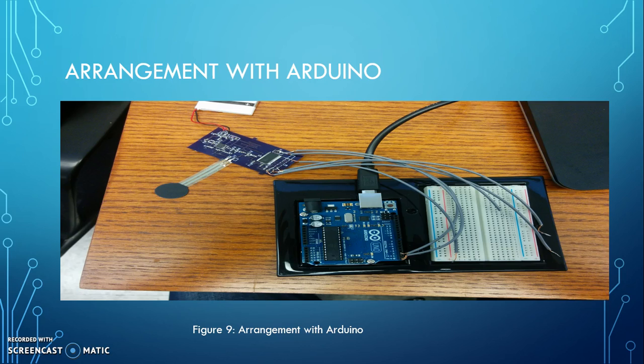And here is the picture of Arduino arrangement, and for the data collection using Arduino from the hardware, I used a serial monitor named CoolTerm. I didn't use Arduino serial monitor since it does not allow us to store data in a text file. I stored the data in a text file. I used MATLAB to read that data and plot it later.